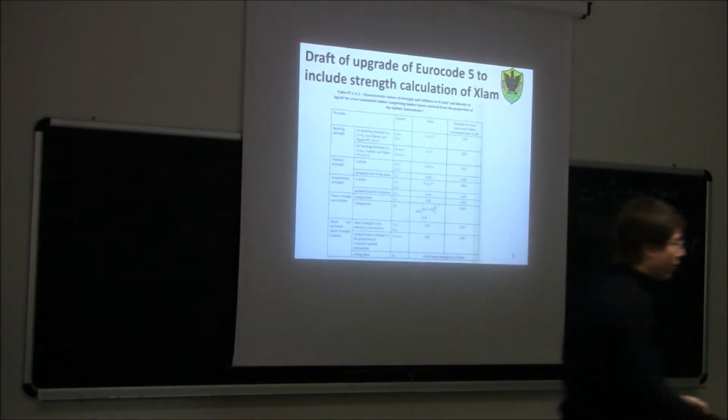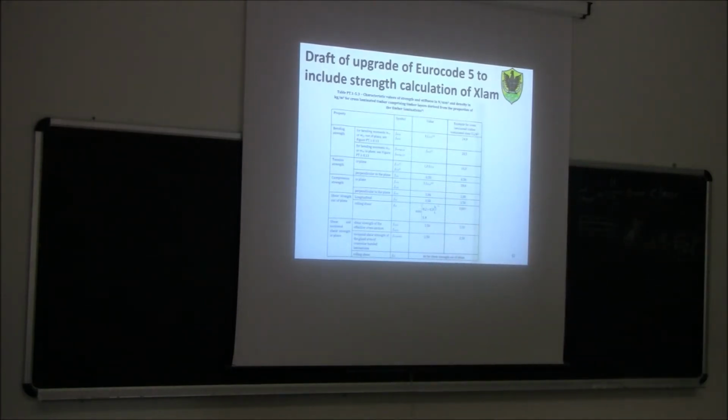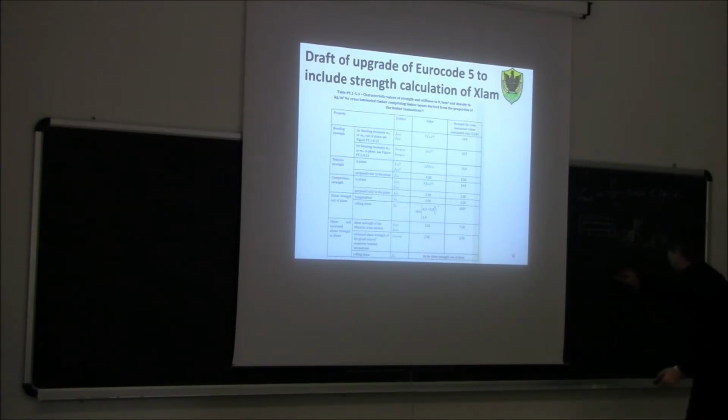So you are designing a cross-slab panel, subjected to axial force, for example compression, because you're using it for a wall. So you're interested in the compression strength parallel to the edge for this panel. How can you calculate this? You go here, compression strength, in plane or perpendicular to the plane? In plane, for example, because we are studying a wall like this.